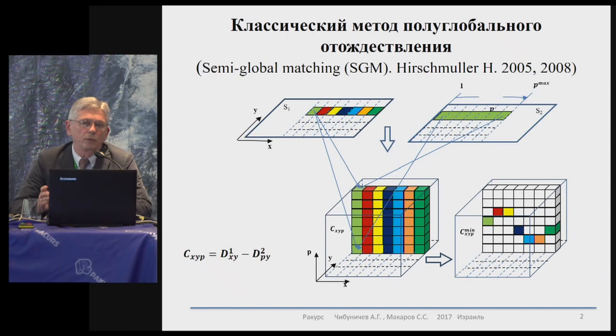Knowing the lateral parallax, we can get a matching point and get three coordinates x, y, z within the system of coordinates of an object. And it seems to be a ready-to-use point cloud with a 1 pixel resolution or step. But this is a simple algorithm which is just the first approximation for acquisition of this point cloud.